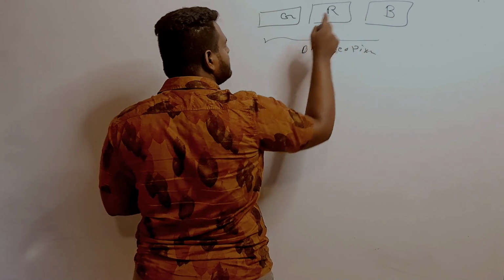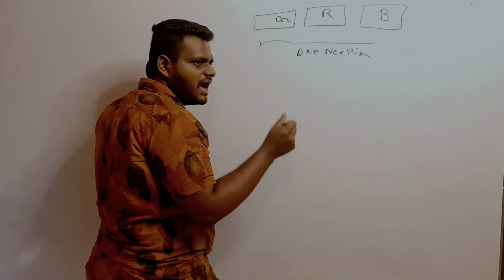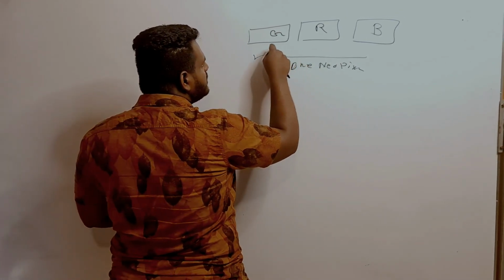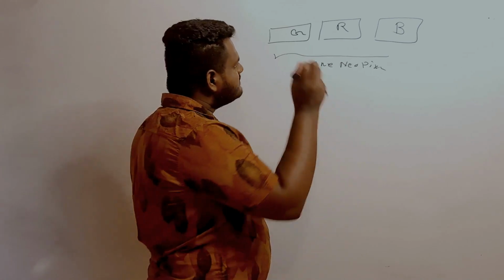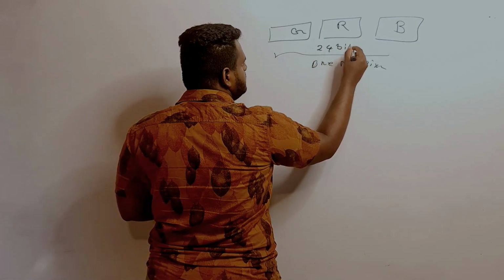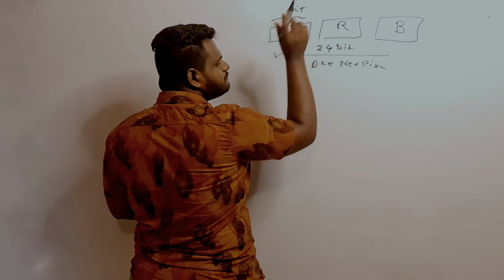That is the GRB pattern we have to send to light up any one pixel. We write this GRB value to the NeoPixel. So this is a 24-bit data stream, and each color consists of 8 bits of data.